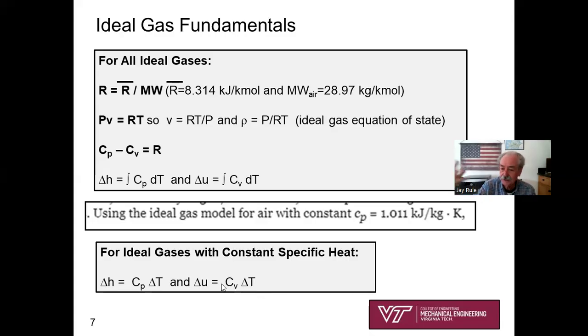And looking ahead towards other problems, or a quiz, what if you're given Cp in a problem, told to hold it constant, but you found that you had to use, you're looking for delta little u. Gosh, think that instructor's playing a trick on me. No, you need Cv, so you remember in your head that Cp minus Cv equals R for all ideal gases. So if you're given Cp and you need to find Cv, Cp minus Cv is equal to R.